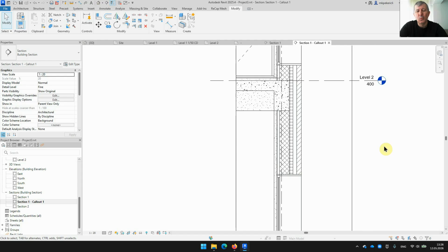Normally my students suggest in the third year, why don't we just take this, create a drawing and take it to AutoCAD and use it there. The problem is, if something changes in your BIM model, your AutoCAD drawing will be something else, something created in another software environment. With BIM, we want to make sure that changes are also changing our drawing. For that purpose, I will basically be tracing the drawings here.